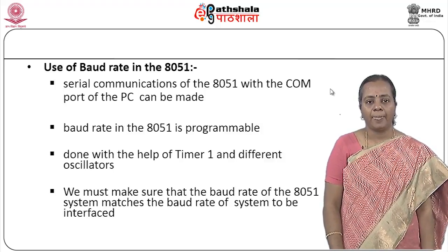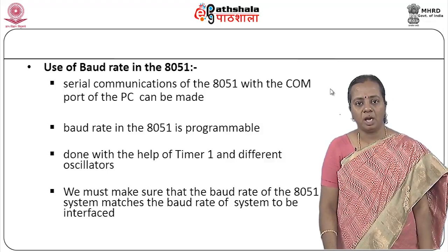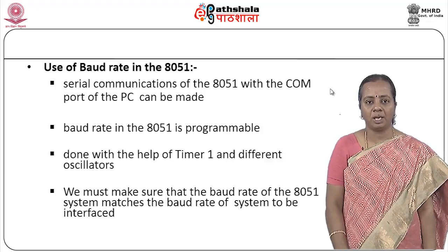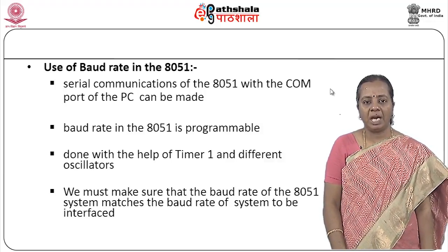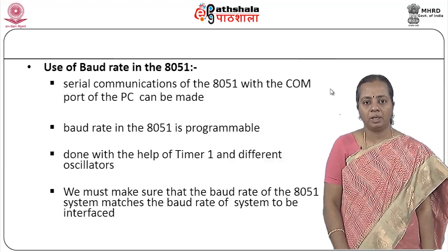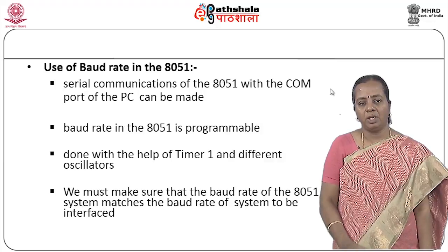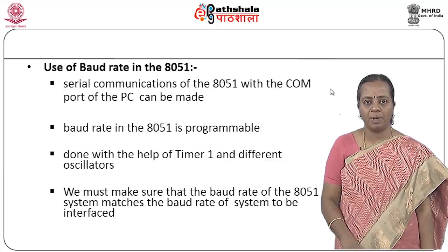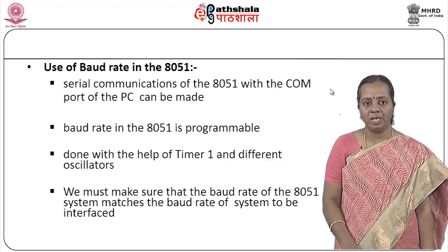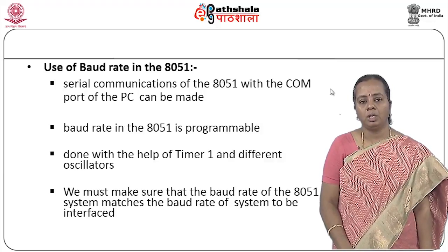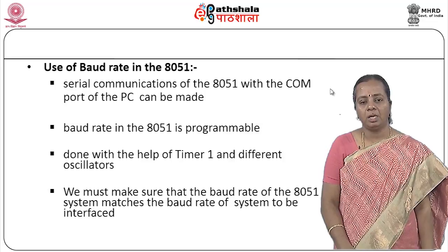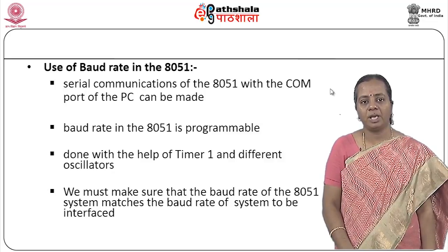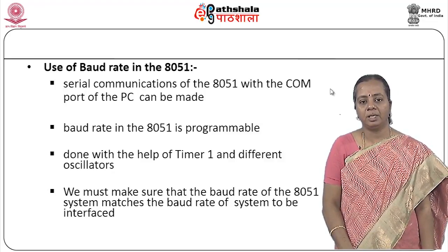Anyway, when looking at the communication of the 8051 with the outside world, or from the outside world to the inside through serial communication, we definitely can't handle it directly. The data should be converted either from parallel form to serial form or from serial form to parallel form. This is done by some interfaces, and with those interfaces only will we be in a position to process or read the data properly in the 8051. How this is achieved will be dealt with in detail in the next lecture.